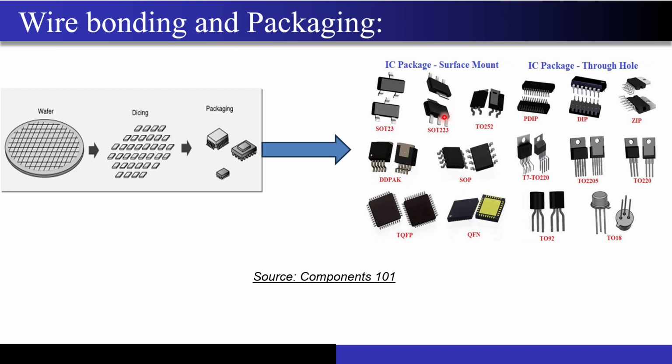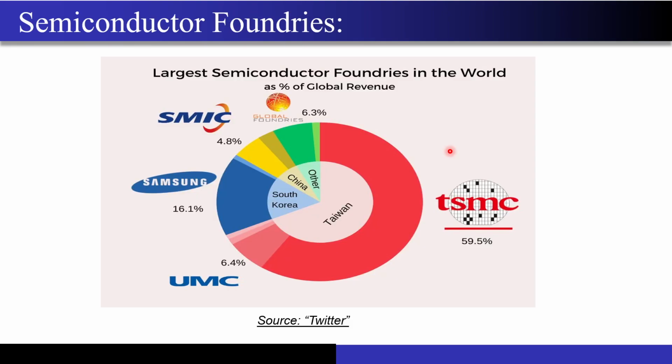So if you are doing something on the PCB, you will see most of the high frequency packages, maybe from some different companies for the power amplifier, low noise amplifier. So they will be available in this particular package. Why not this particular package? Because you can see the lead lengths are so much higher. They are going to introduce so much parasitics, right? So it does not make sense to use these kinds of packages at a higher frequency. Higher frequency means I'm talking about 2.4, 8, 10 up to 20, 30 gigahertz, right? So I hope this is very much clear.